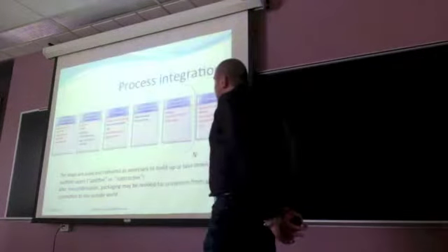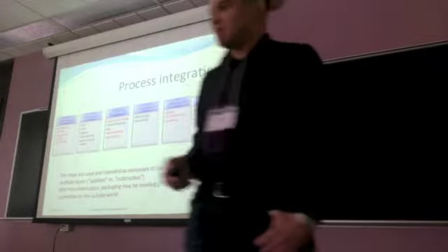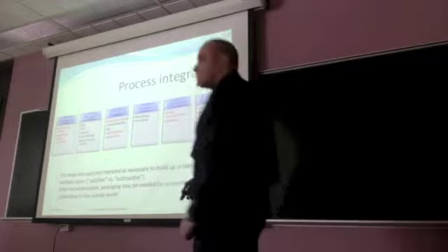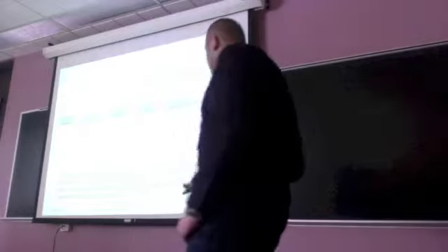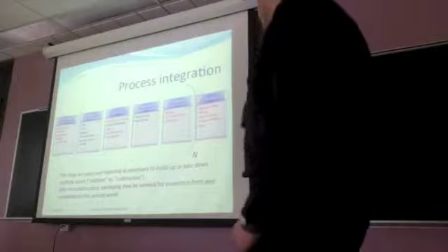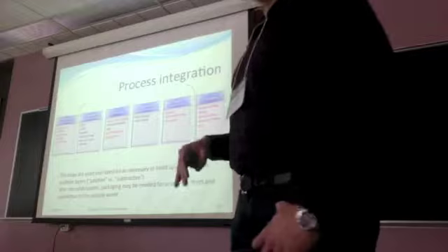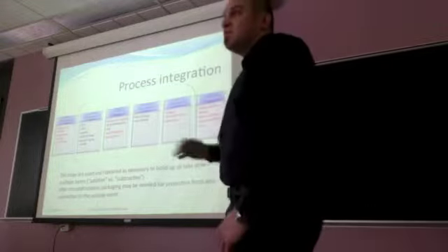So when the fabrication of your device is done, sometimes you need to connect this device to the outside world. So you need to do packaging. This is why after microfabrication, packaging may be needed for protection and for connection to the outside world. We have some techniques. We have wafer dicing. We can dice the wafer to get chips or dies. We can do wire bonding, and we can also do characterization and test, electrical test.